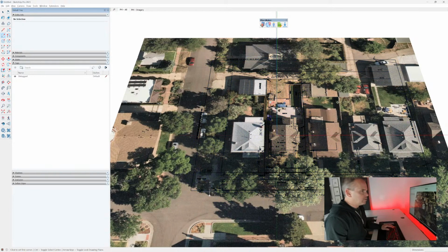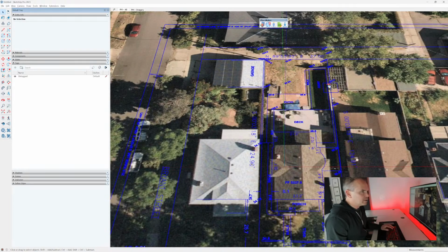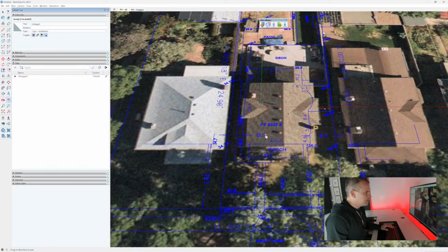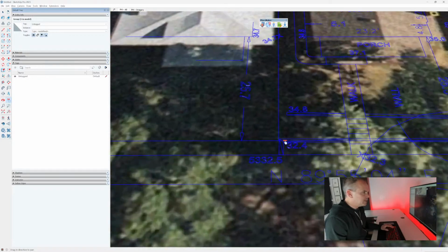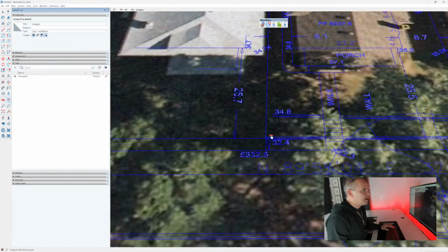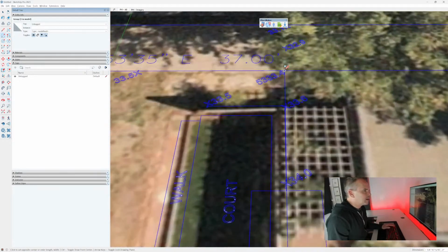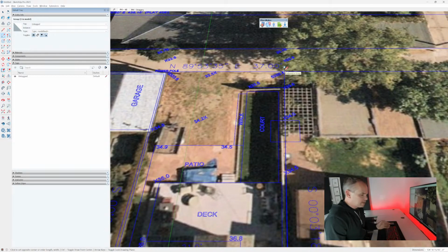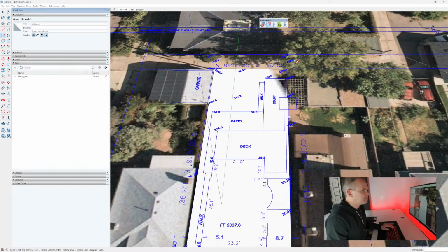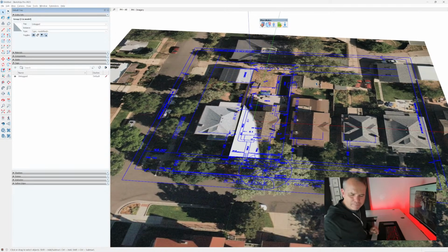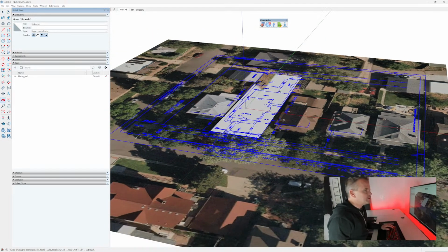And now I'm going to make sure that everything looks pretty decent still. My lot lines are kind of where they should be. And then I'll use my rectangle tool. All right, so as I go up here and get close, you can see it's long distance first, 37 second. Okay, so we're going to type in 124.9 feet, 37 feet, enter. All right, I feel like that's what I did the first time, but maybe I'm wrong. All right, so let's keep rocking here.